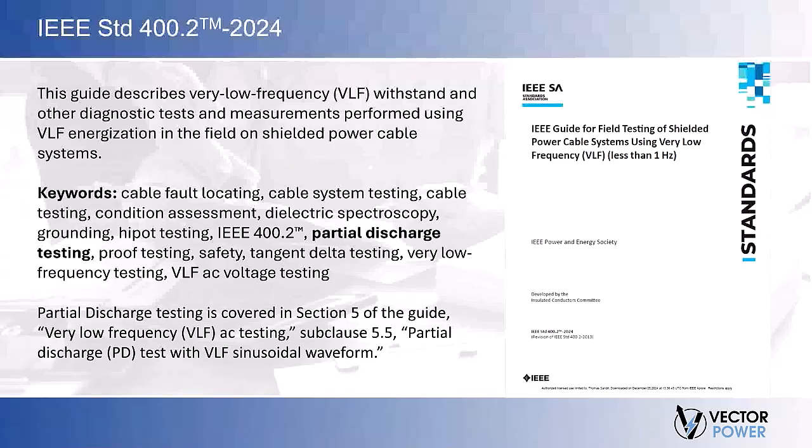How about we now talk about what are the resources that we can turn to better understand the complexities, process, and analysis of partial discharge. Among these we have the IEEE standard 400.2 2024. This guide describes very low frequency, or VLF, withstand and other diagnostic tests and measurements performed using VLF energization in the field on shielded power cable systems.